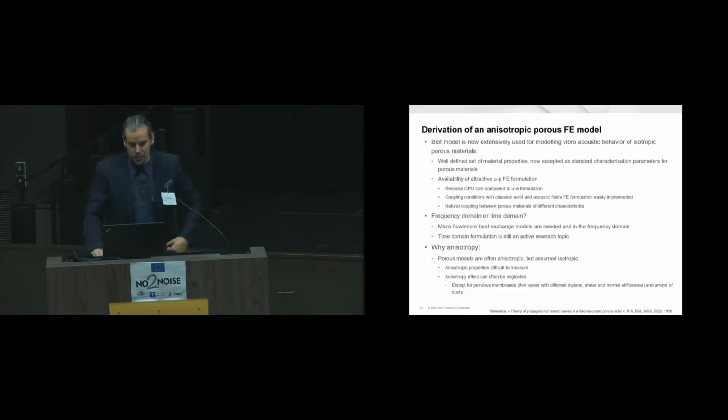Okay, you've seen how I derived the finite elements for fluids. Basically, the idea for porous material is exactly the same. We start from a PDE. We create a weak form for this PDE, do some clever use of the Green theorem and partial integration, and end up with a weak form with natural boundary conditions. And then we discretize this weak form. The trick is to use a PDE and apply the Green theorem cleverly so that the natural boundary conditions we get are useful, either as themselves or because they allow easy coupling.